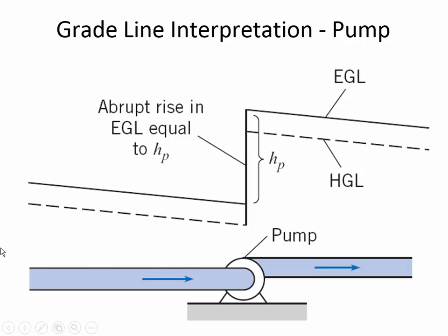that's shown in the problem that you're working. And here you can notice that the lines are going downhill, downward, because of the energy loss due to pipe friction, but then the main characteristic is a sudden increase in pressure due to a pump. That's what a pump does, it has a sudden boost, and then after the pump, the line is sloping downward again because you still have energy losses even after a pump.